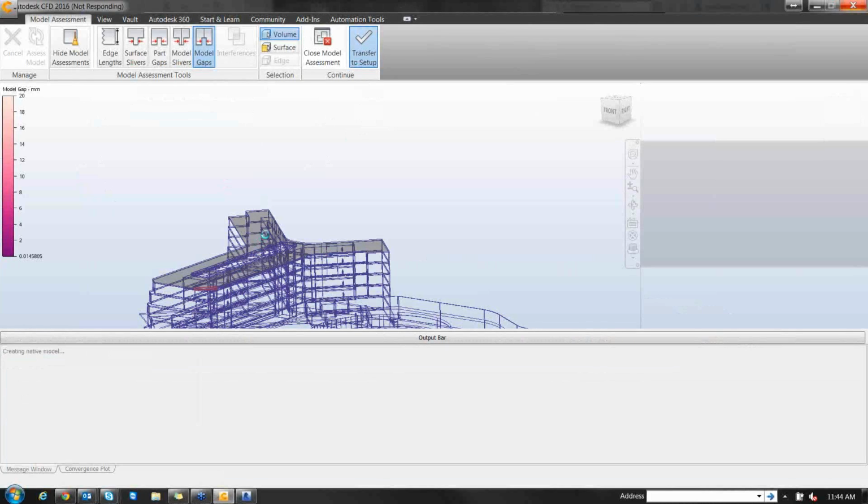The stream function is actually a 2D output, and then you can put an ISO surface in here and switch it to the nodal aspect ratio result and just find your most deformed elements in your model, and then just start zooming in and discovering things that way. Great diagnostic tool, but it requires going through a few different steps to finally get to that, and then waiting for it to mesh if it's a complex model.